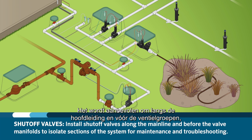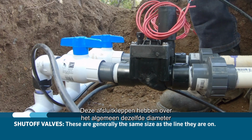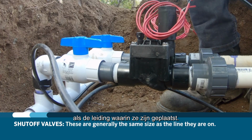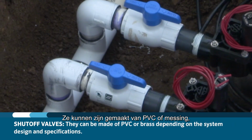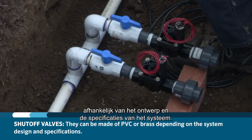Along the mainline and before the valve manifolds, it's recommended that shutoff valves be installed to isolate sections of the system for maintenance and troubleshooting. These are generally the same size as the line they are on. They can be made of PVC or brass depending on the system design and specifications.